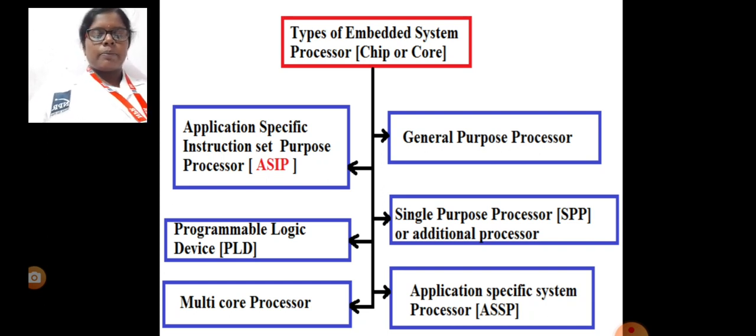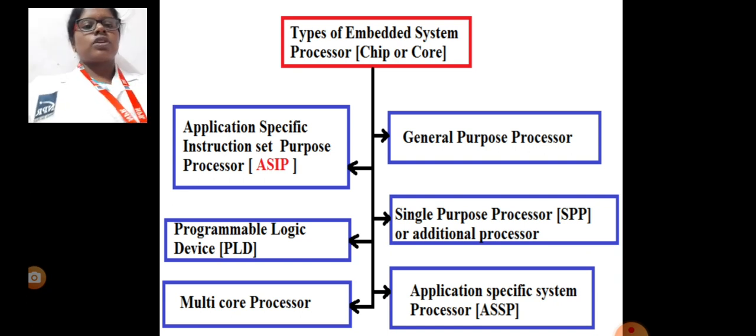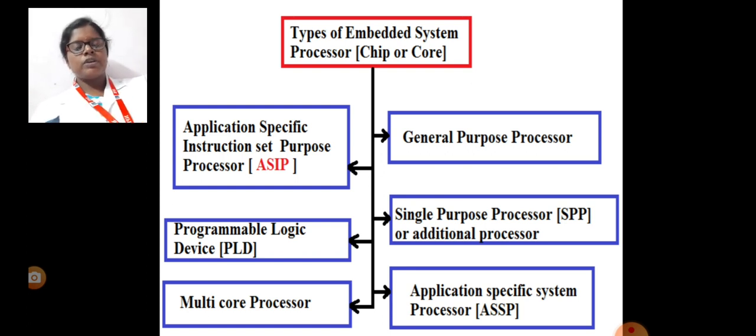Power should separately power the external IO. It should give power to the external IO port, and timer, clock, and reset circuits. Clock and reset circuits need to be specially designed to be free from any radio frequency interference. An IO device may dissipate more power than other internal units of the processor.